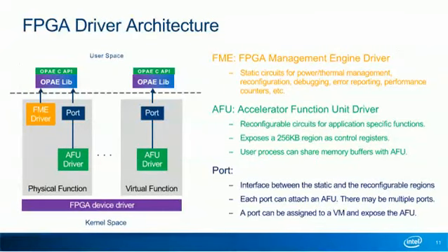Sitting underneath the OPAE layer is the FPGA driver. This slide shows the FPGA driver architecture. This is what's interacting with the FPGA. In a non-virtualized environment, the host interacts with the FPGA through just a physical function. In the virtualized environment, as shown in this diagram, the driver in SR-IOV mode allows the host to use the physical function, PF, to access management functions, while a virtual machine uses a virtual function, VF, to access the AFU.